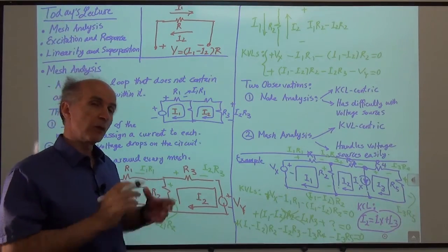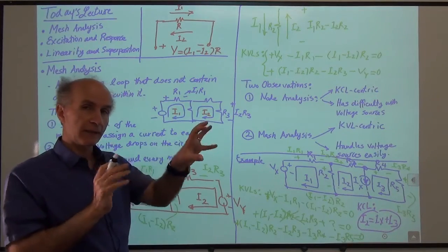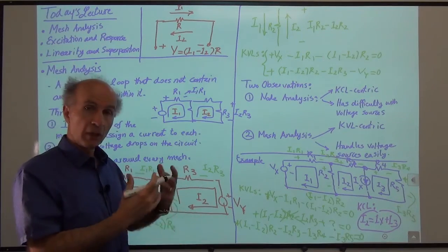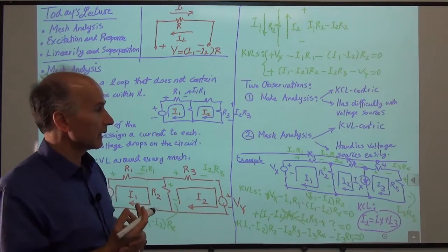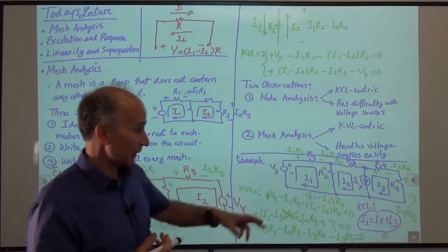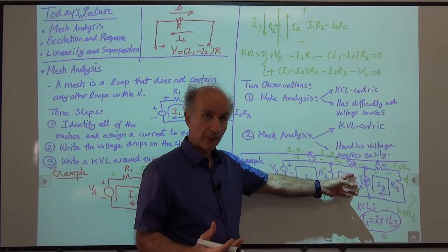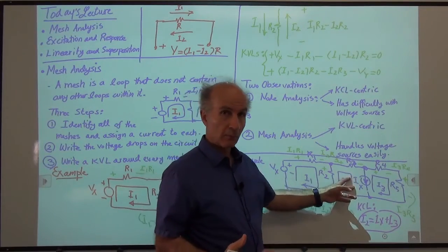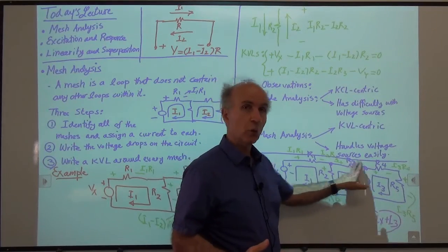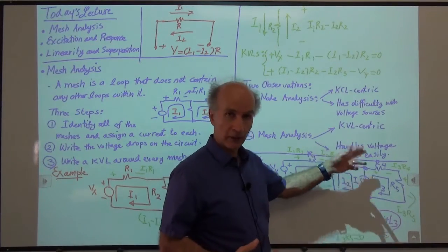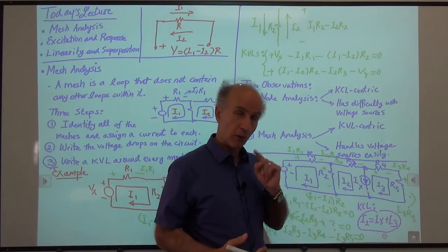All right? So if you remember the duality between node analysis and mesh analysis, these things become relatively easy to remember. So what we see is that in the case of mesh analysis, if we have a current source, the current source gives us trouble. And what we do is we merge the two meshes that share that current source into one mesh. So we can write our KVL around that mesh. We lose one KVL.